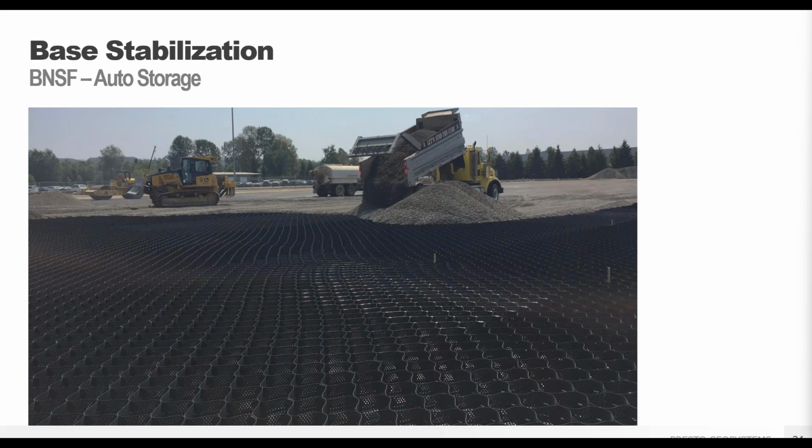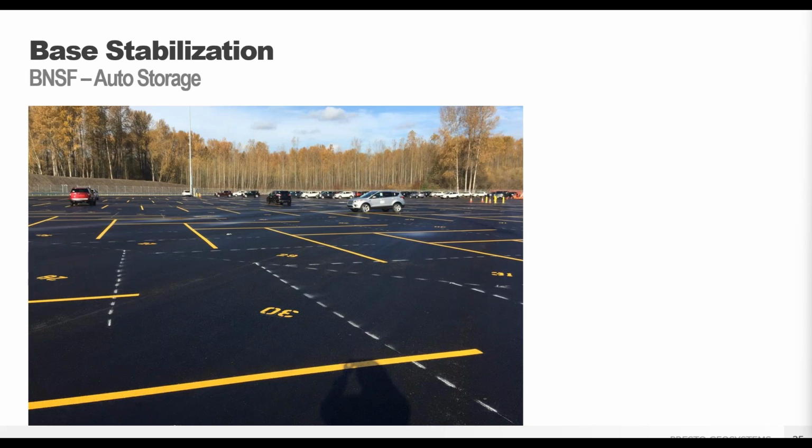The dump trucks can back right up to the GeoWeb, dumping the infill material and then spreading via bulldozer. The material supports loading immediately after filling, no cure time needed, serving as its own site access road for construction. And here's the finished surface.